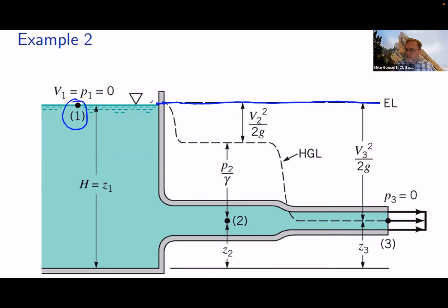And then as we go into this pipe, we have a drop off because of this changing diameter, okay? So we have a drop off here until we get to a more consistent diameter here. I'm just going to call it D2 because point number 2 is in there, but some diameter there. And then we're pretty consistent, right? So here's the hydraulic grade line going across.